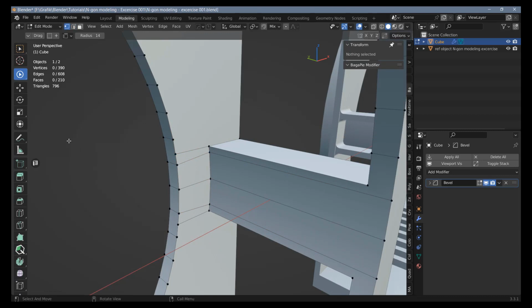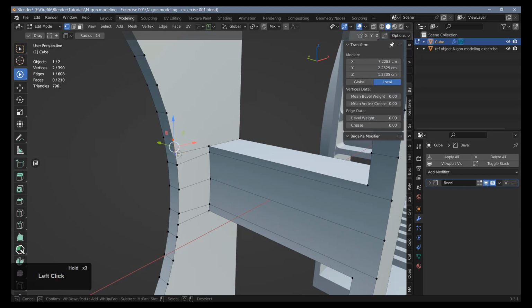As far as selections are concerned, I'm using a paid add-on called Power Select, and what this does for me, and Blender doesn't do that, is the first vertex that I select will automatically be the active vertex, so no need for me to shift left click twice to turn a vertex into an active vertex. The first one will always be the active vertex.